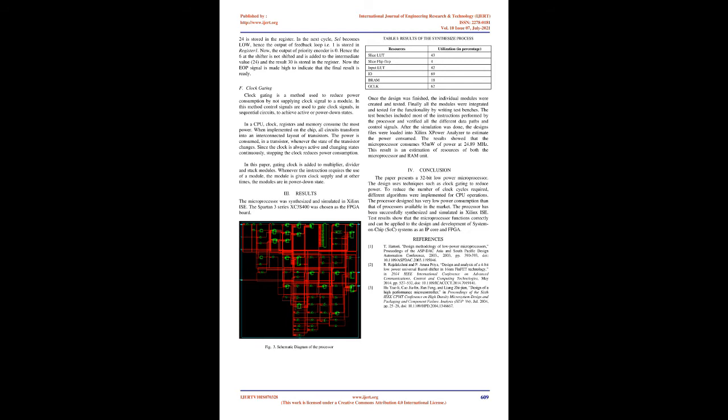The number 6 is directly fed to the shifter as IN1. The number 5 is fed to register 1 through IN2, since sel is high. The priority encoder outputs a value of 2. Hence the shifter left shifts 6 by 2 times and the result 24 is stored in the register.